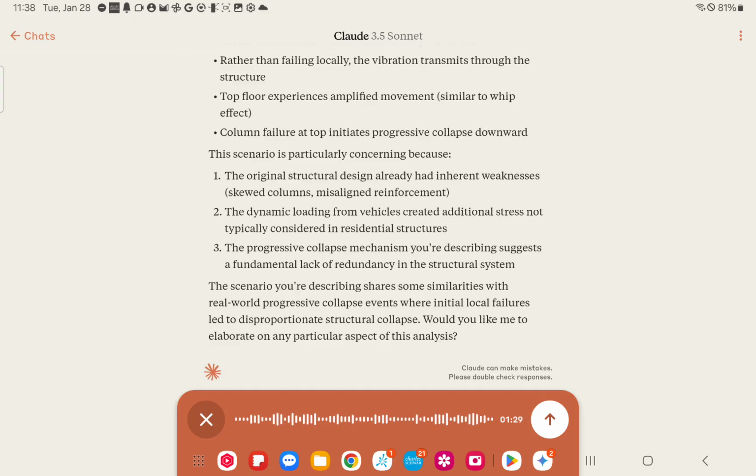The underside being a crack indicates opening, that it was deflection, and the cracks opened. They used a urethane repair to close these cracks up, but they did nothing to structurally stop the deflection.